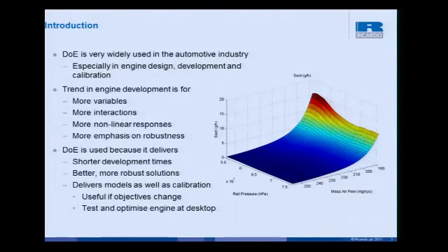They interact together, and a lot of responses are very non-linear, particularly where you're modelling engine emissions. If you like, the physics of emissions generation are exponential type functions, and they're very sensitive to small changes in pressure or temperature.